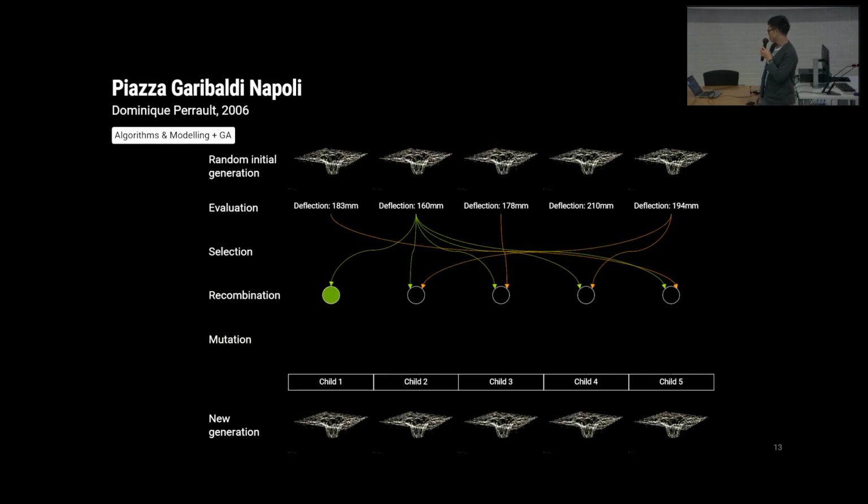So optimization at this stage is where we come up with a design space where we have different parameters that we can play with, and we let the computer go through many different iterations. These iterations are evaluated, assessed for different objectives, and then we pick the best ones, and we do this over many iterations until we find the best solutions. And then we always get a pool of optimal solutions based on different objectives. So together with the architects or designers, you can go through and pick and choose specific structural solutions that might fit best to that architectural design intent.